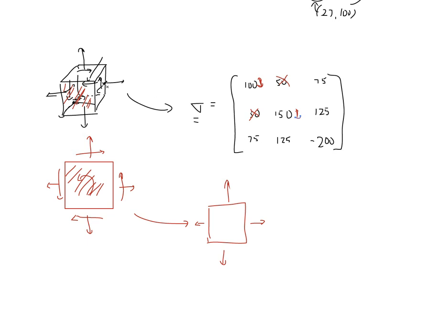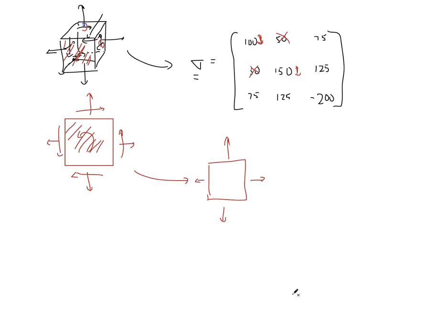In the same way, I can rotate the other sides of the surface until there is some element that only experiences normal stresses, whatever those may be, positive or negative. So some rotation exists of this three-dimensional element where shear is completely gone.